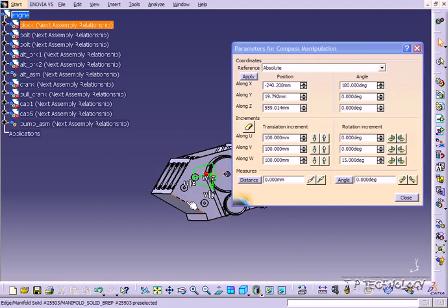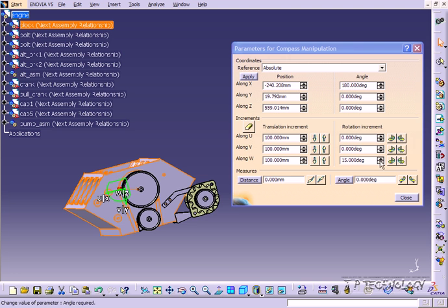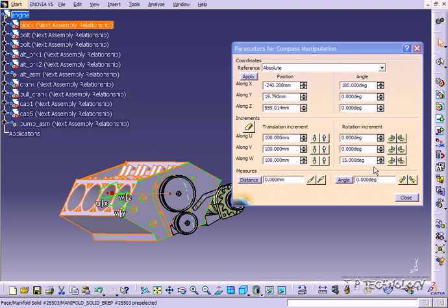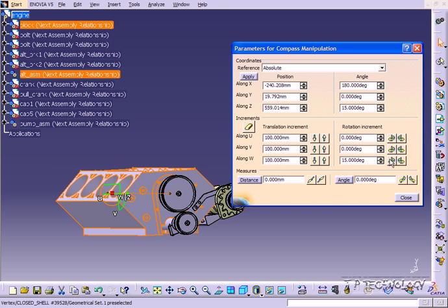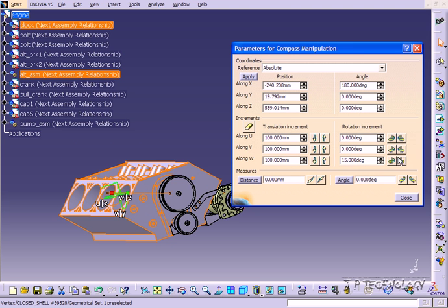So now again, you're able to go through the assembly and use the hierarchy system and pick which parts or assemblies you want to move. To start off, let's move just the engine block. So let's double click engine, just highlight the engine block, and we have it rotating around the W axis at 15 degrees. Let's just try it out. You can see how the whole block is rotating 15 degrees every time we click. And again, you can do the same thing if you click on the plane and rotate about it too.